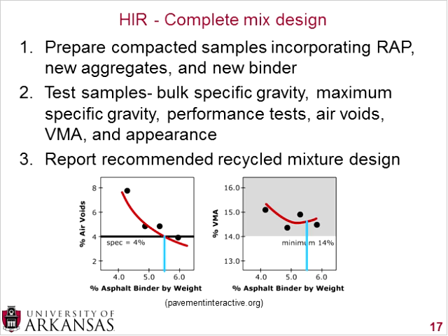There's no studies out there that say HIR will last longer than a traditional hot mix design or shorter than a traditional hot mix design, because there really are just so many variables. But this is one thing you could do, is run concurrent mix designs and compare them at the same time.